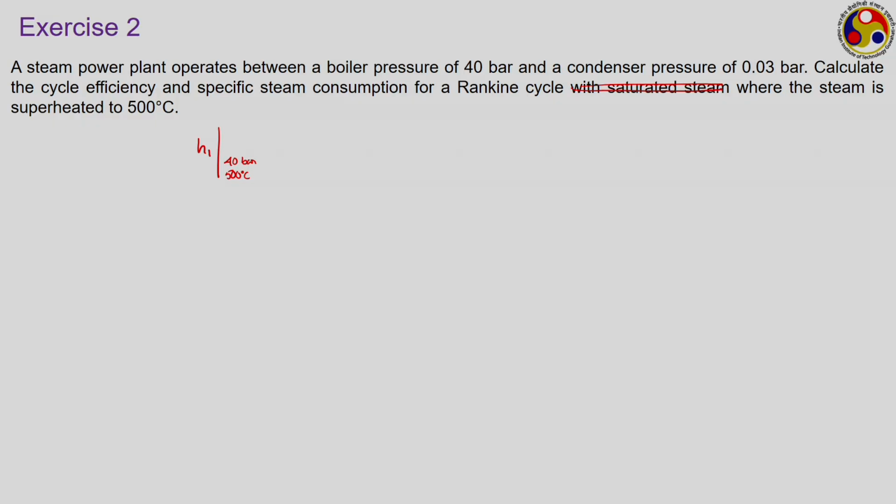So, to solve this, you have to use the superheated vapor table. These numbers will be coming as H1 equal to 3485.5 kilojoule per kg, and your S1 entropy at the same state is 8.1933 kilojoule per kg Kelvin.